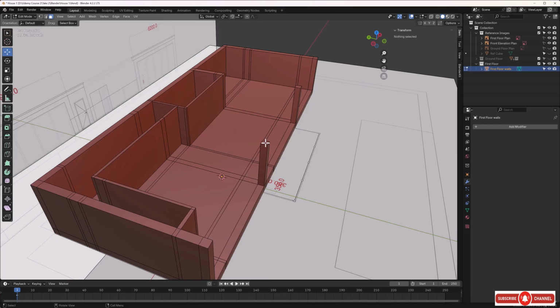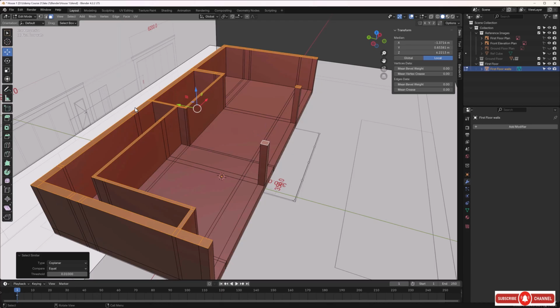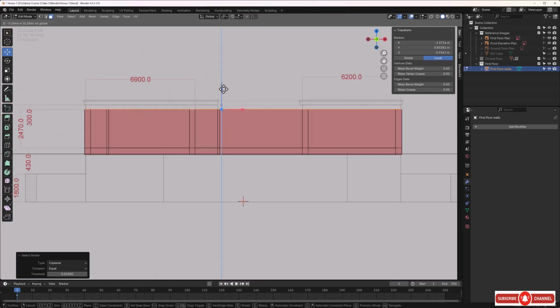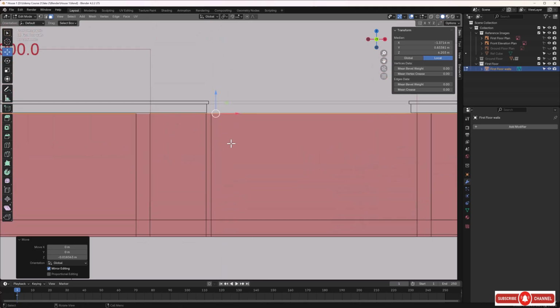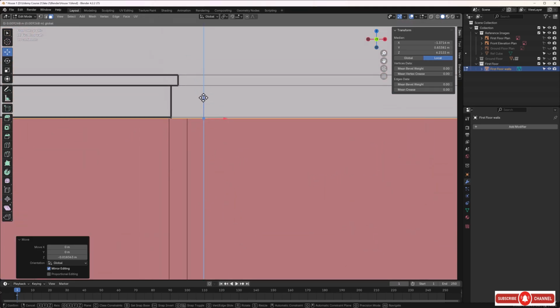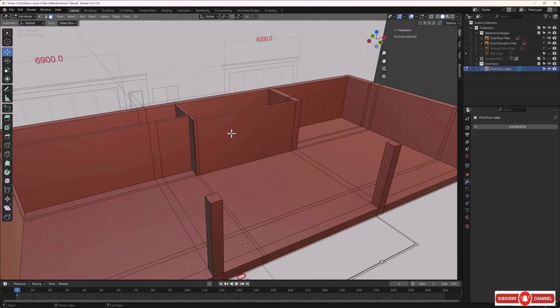Then let's select a face just on the top here that we just extruded. Go over to select again. Select similar and coplanar. Let's press 1 and let's bring that to where we need it to be, which is just level with the roof line like that. Does it want to be any more? Let's just zoom in a little bit and maybe take it up just a tiny bit more to about there like that. Okay, so what's next?